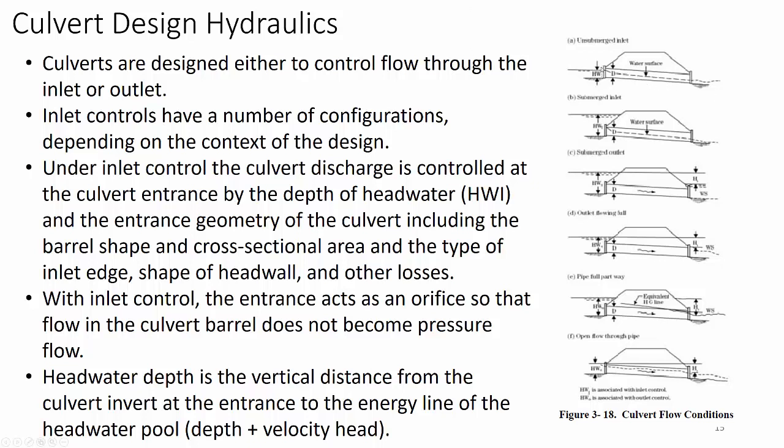Most of the time, you don't want the things to flood upstream, and so you have inlet control. You want this to drain so that it doesn't top over. So you control the flow up here, and you don't control below. Sometimes you control below because you have adequate storage above. That just depends on your configuration, but most of the time it's inlet control.